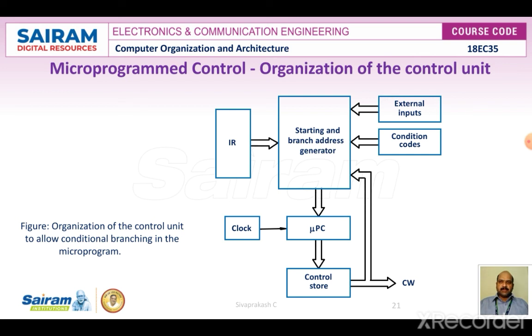Third, when an end micro instruction is encountered, the microprogram counter is loaded with the address of the first CW, nothing but the control word, in the micro routine for the instruction fetch cycle. In such a way, the organization of the microprogrammed control works.